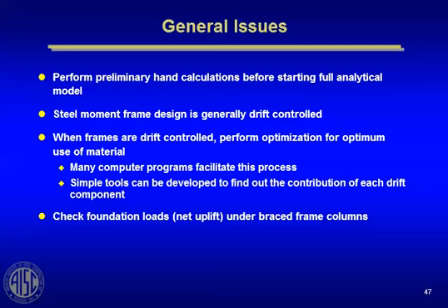And it's particularly good for a seismic zone, because that moment frame then can be your so-called backup system toward the tail end of the earthquake. When the braced frame connections have maybe buckled or failed, you've got that ductile moment frame that's giving you that post-earthquake resistance that you like to have. So these are just some of the general issues you've got to think about.